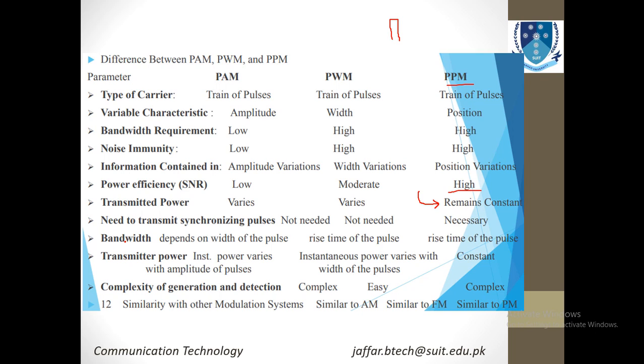If you talk about the bandwidth requirements, in PAM it depends upon the width of the pulse. In PWM, the bandwidth is dependent upon the rise time of the pulse, and in PPM it also depends upon the rise time of the pulse.